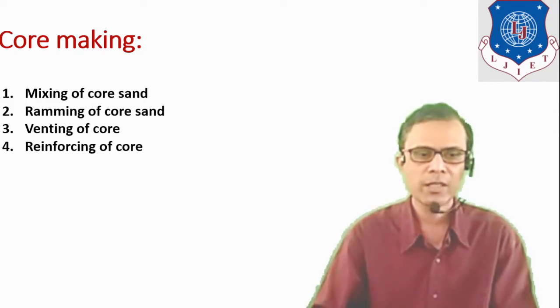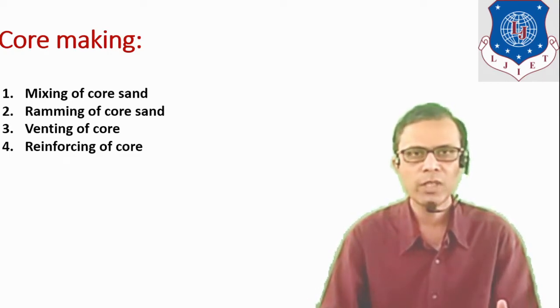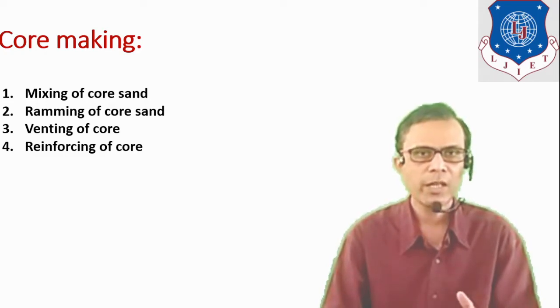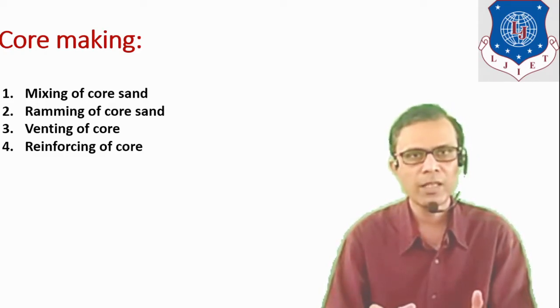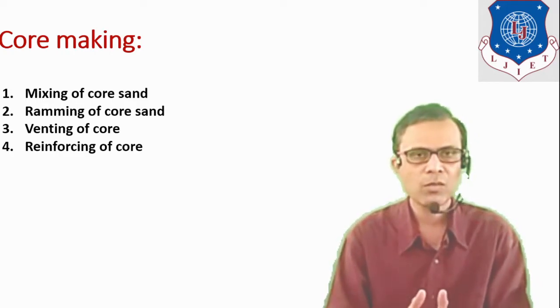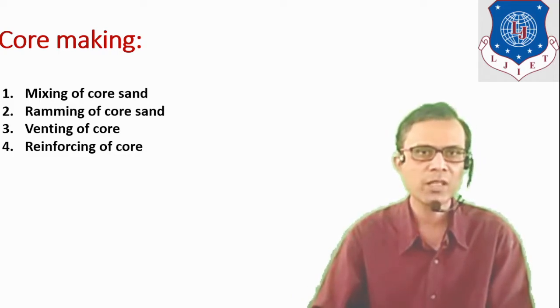Next step is reinforcing of the core. Reinforcing means to provide internal strength to the core material, as it has to withstand thermal stresses, and it has to withstand some ramming force or pressure also. It should be able to withstand all those pressures or thermal stresses. So that's why reinforcing of the core is done by internal metallic wires.